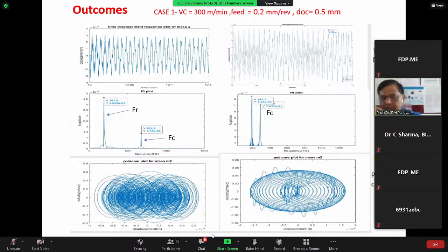As you can see, the velocity and displacement diagram. FFT, that is a mathematical transformation of that signal, gives us an idea about the frequency. The first one, the time response, gives us an idea about the amplitude of vibration. Okay, so now when we are talking about this, what are we getting out of this?